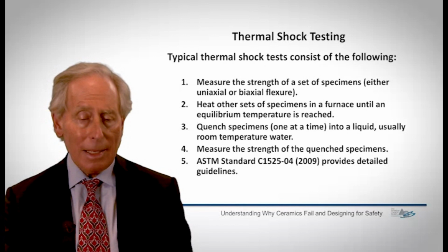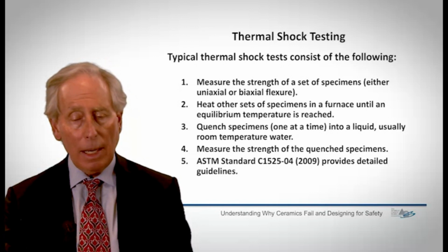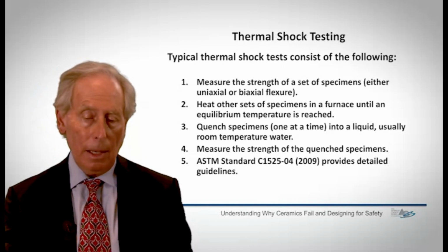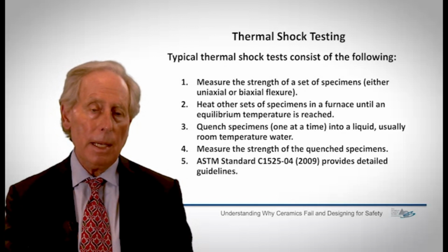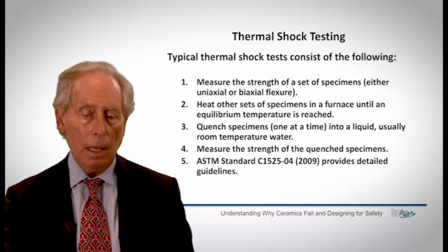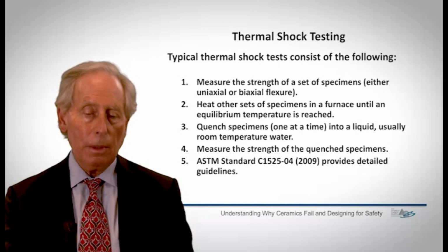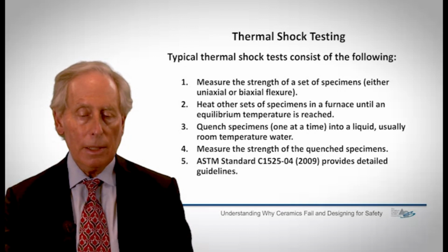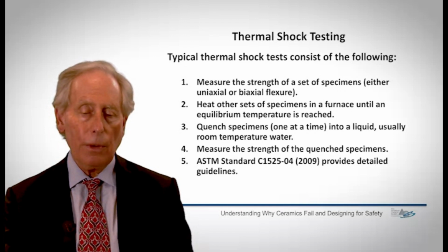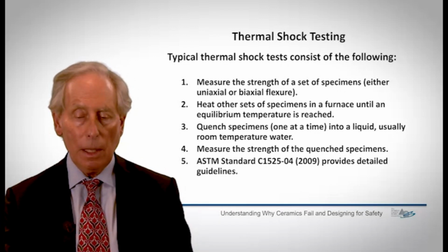And there is guidance on this. So the ASTM standard, you see here, provides some detailed guidelines on how you do these kinds of tests. One has to be cautious, though, because if you're quenching in water, and in real life the medium that you're working in is not water, you have to be careful that you're not getting misleading information from the water quench. It doesn't always transfer from one kind of quench medium to another.